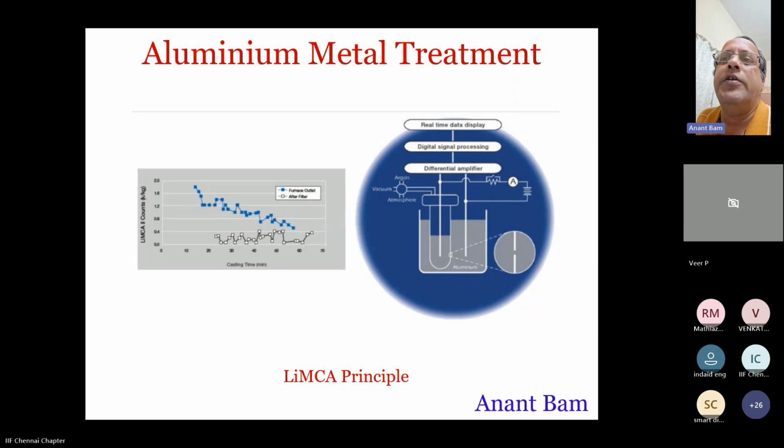And naturally, you see a pulse in voltage as well as a pulse in current. The more pulses, the more oxide inclusions in that sample. The higher the amplitude of pulses, the larger the size of that oxide inclusion. So you get to know how much and how bad the oxide content in the liquid metal is in a very short time.